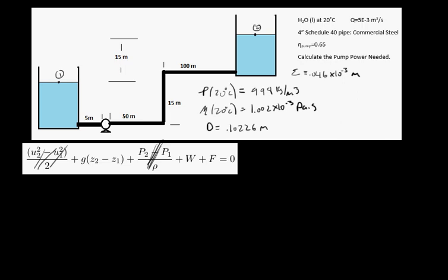Okay, so with all that given information, we will be able to calculate what the pumping power is. The first thing that we're going to want to do is determine what the fluid velocity is inside the pipe. So U is going to equal, well, we know from a continuity expression that Q is equal to U times the cross-sectional area, and if we solve that and substitute pi d squared over 4 in for the cross-sectional area, we get this expression, pi d squared.